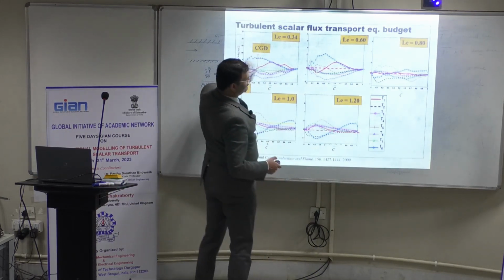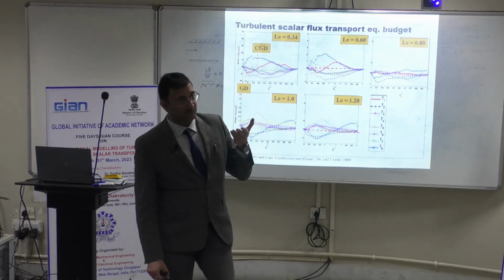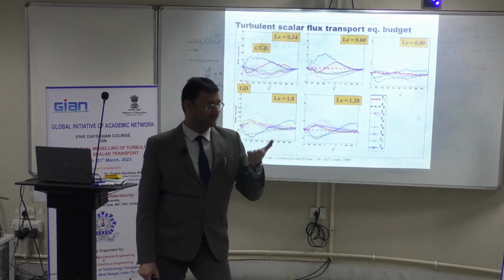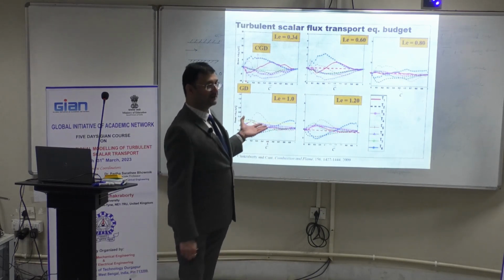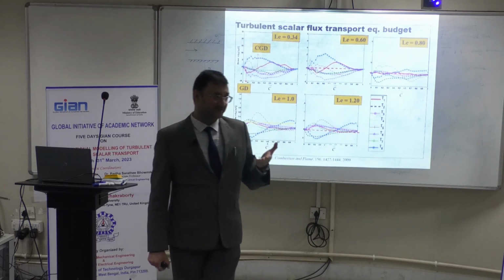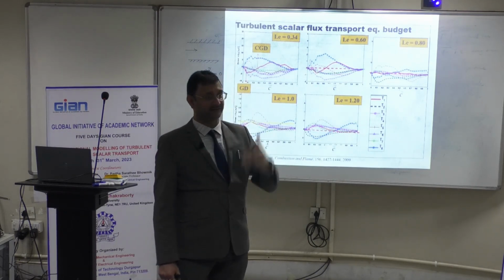High positive values of T4 promote positive values of scalar flux. In this statistically 1D plane, a positive value of scalar flux, we discussed already, means counter gradient transport.